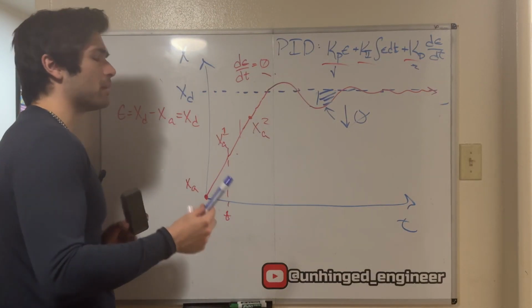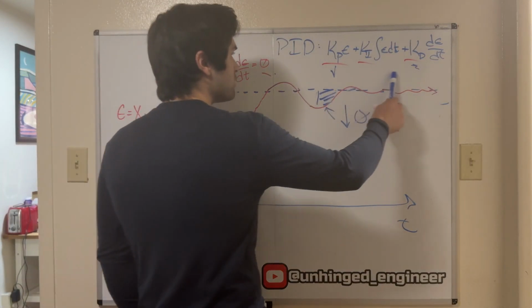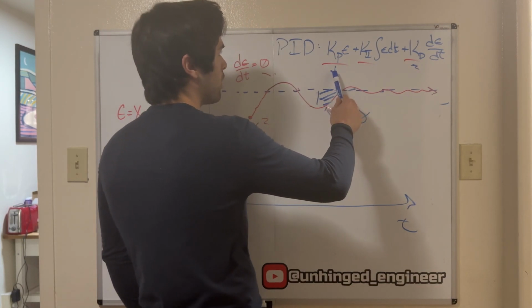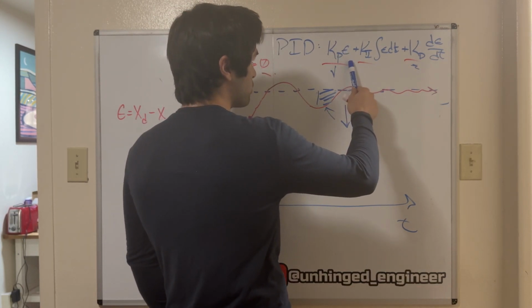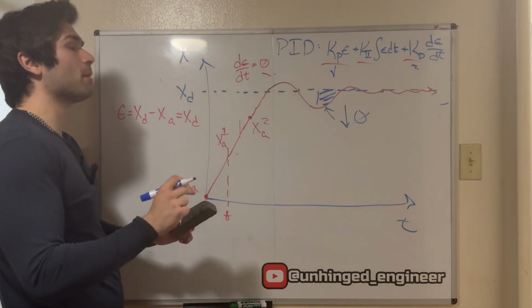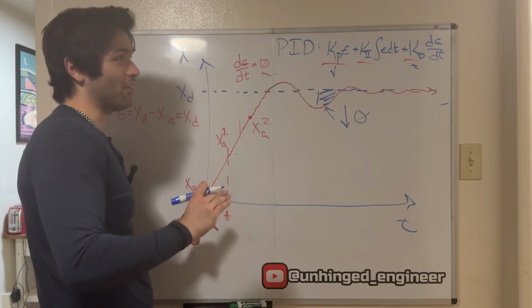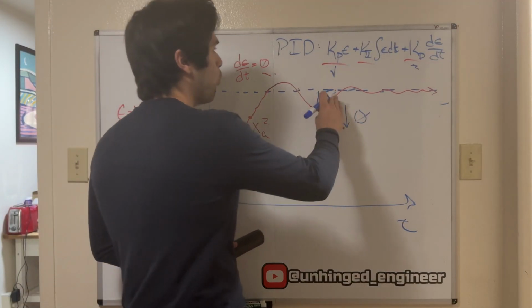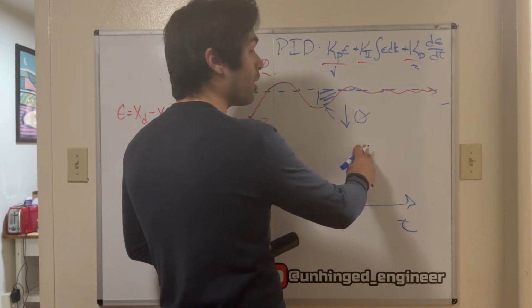And so this is how a PID controller works. There's 3 gains that we multiply by the error: proportional to the error, the integral of the error over time, and the derivative of error. This is all a PID controller is. That's it. There's analog PID controllers that literally wire this out in circuits, so no code required, right?